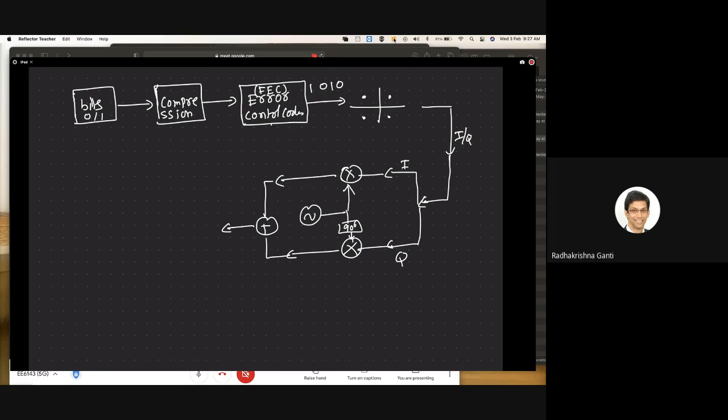For example, when you're calculating the output of your power amplifier, this kind of normalization will help you understand how much the output power is. Practically you do not normalize, but when we do the math, it's easier to think of your constellations always normalized to 1. Even your standards will tell you to normalize to 1.